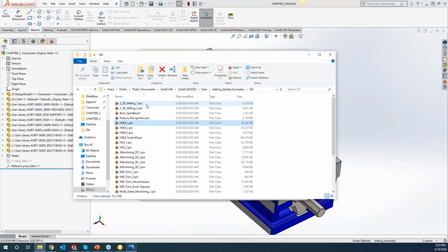There have only been a few vault programs out there that haven't accepted PRZ, but all you have to do is type in the PRZ extension, and it will automatically add it in there for the vault settings. I completely forgot about the vault. If you're working on a vault, checking in and out with a PRZ file is a whole lot easier than checking in a PRT file and then also having to check in the folder that goes along with it. Great point.